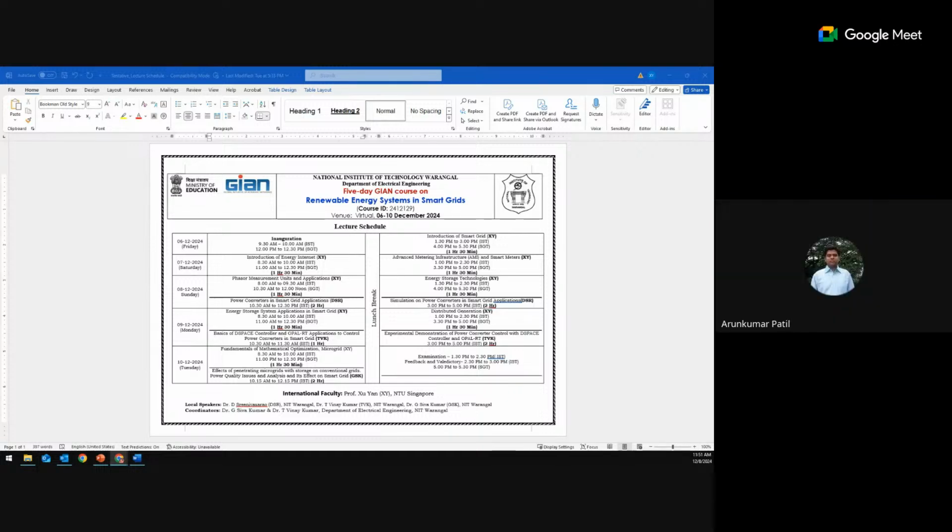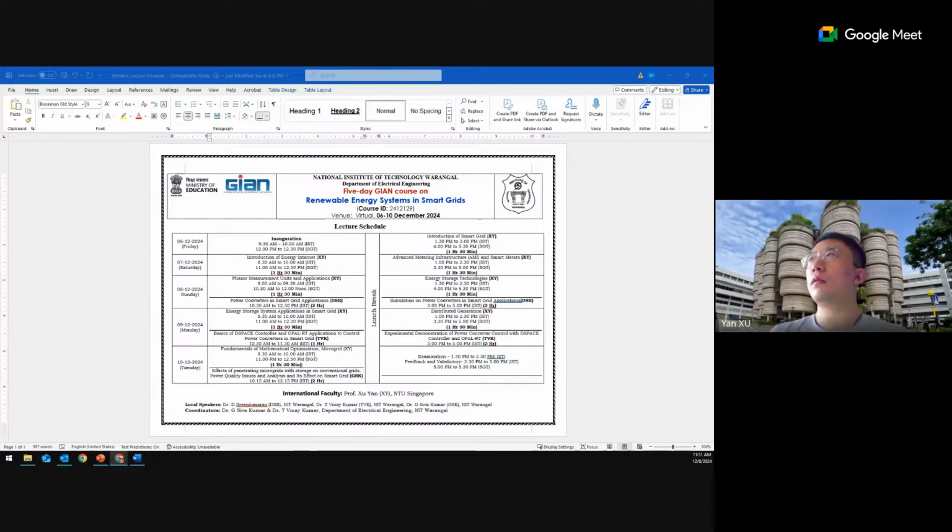Is there any other system, sir, other than OpenRT and RTDS? For offline simulation, actually we use PSSE. Then we set a very small time step, 0.01 second, for simulation. That is also possible, and you can also use PowerFactory. You can also use PSCAD for electromagnetic simulation. So they can also support very high resolution transient simulations. Yeah, PSCAD is also useful.